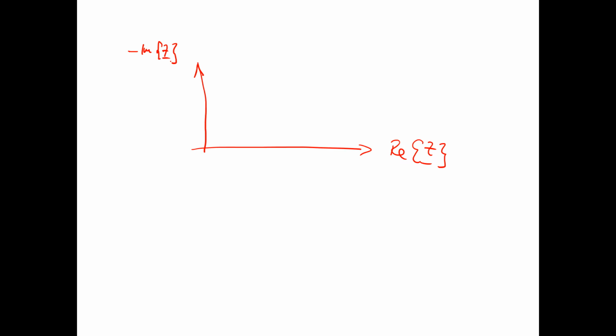I'll write it here, Z is 1 over j omega C. And that means having j in the denominator is minus j over omega C. So whatever we do, this is negative. And we have no mechanisms that react inductively. Therefore, we don't get in the upper right corner. And that was the reason why people said, oh, come on, let's do it that way.